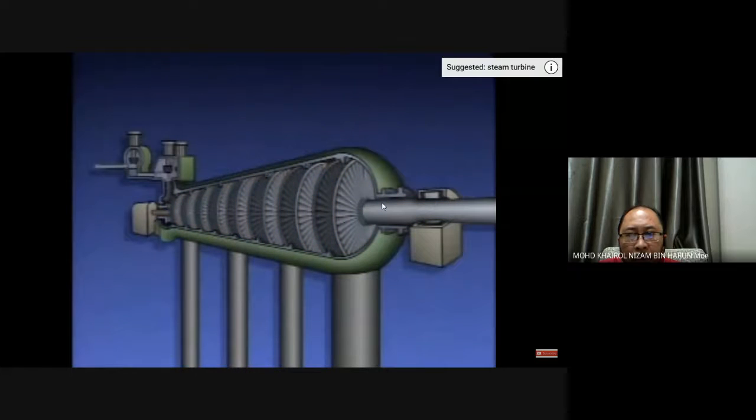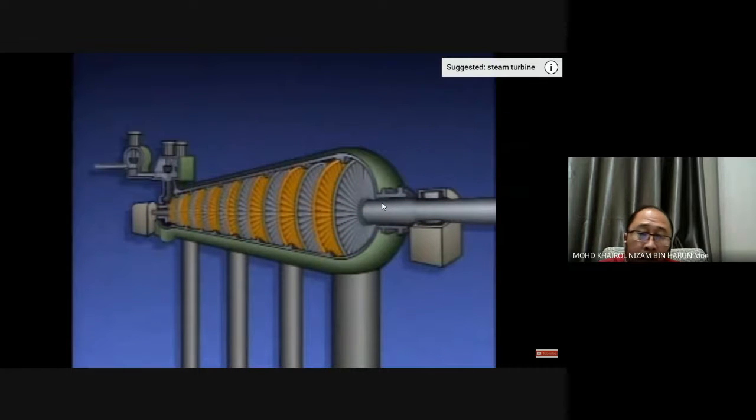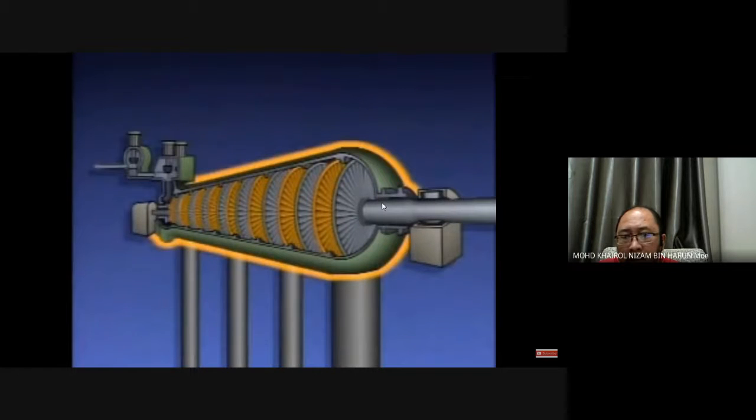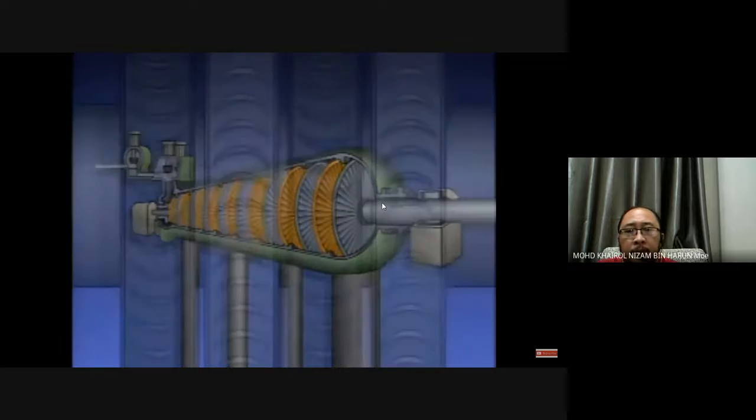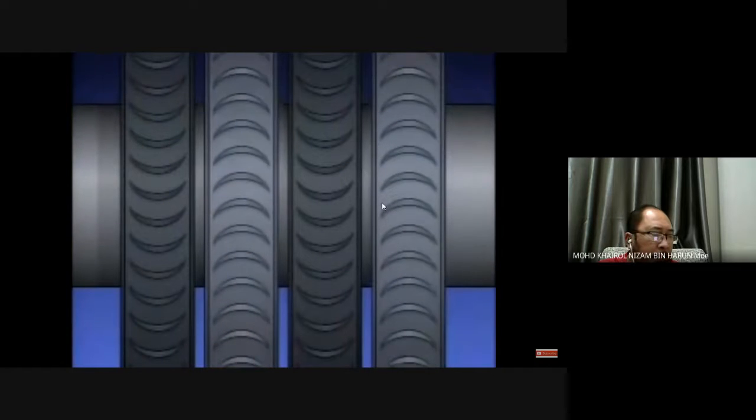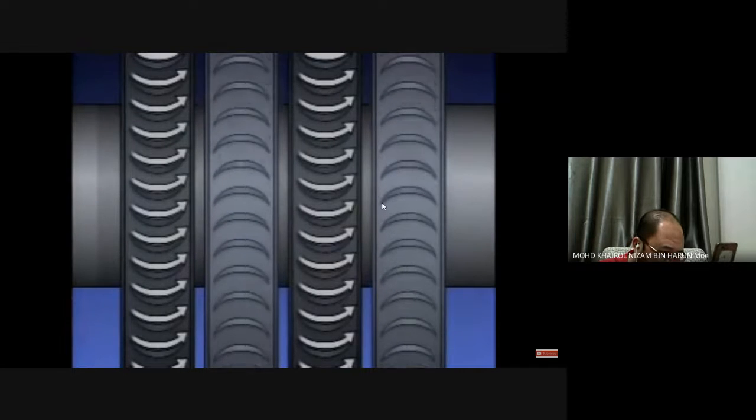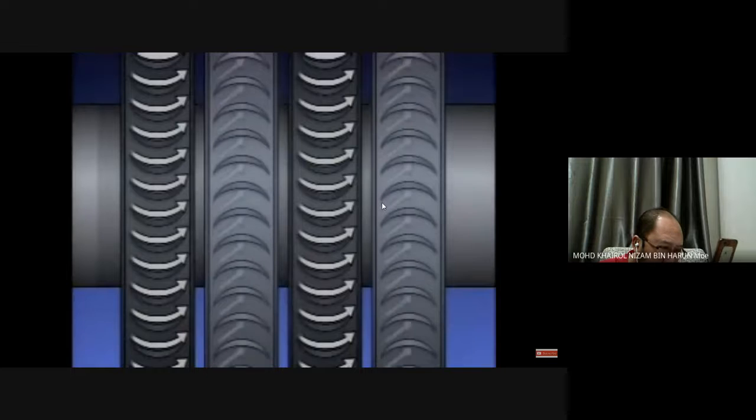Mounted to the turbine casing are diaphragms. They are positioned in the casing between the wheels. The casing and diaphragms are stationary parts of the turbine. Diaphragms are similar to wheels in that they are round hubs and they have blades. The diaphragm blades are sometimes referred to as nozzles. The distinction between diaphragms and wheels is the way they function during turbine operation. Diaphragms are stationary and their blades are fixed in position. Their function is to direct the flow of steam leaving one set of rotating blades into the next set of rotating blades.